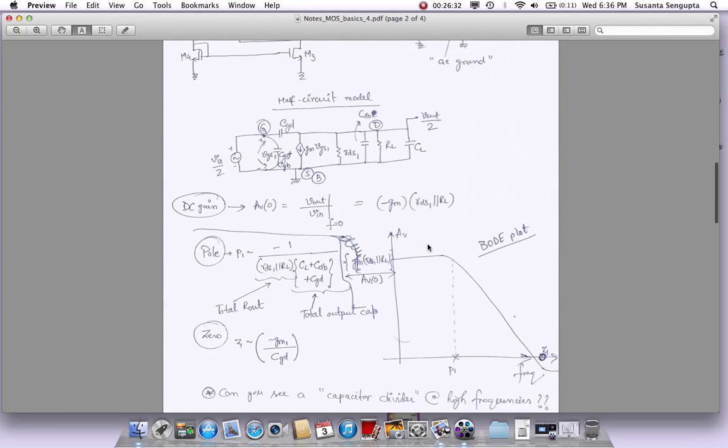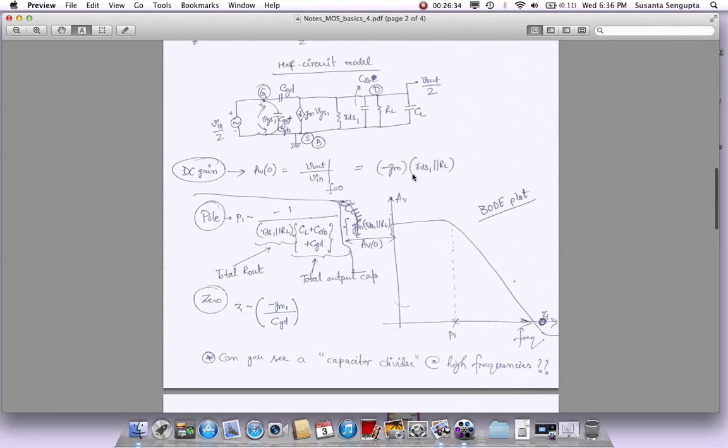The next thing that we are going to find, given that we have got the DC gain because we assumed all my capacitances are absent, and they are really going to be open circuit at that frequency. Remember what I'm trying to do: if I took this circuitry here, I can derive the whole thing by changing the impedance of a capacitance. Let's say CGD. The impedance of a capacitance is going to be 1 over s CGD, right?